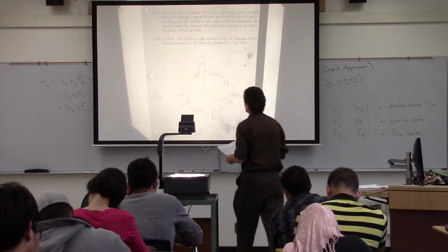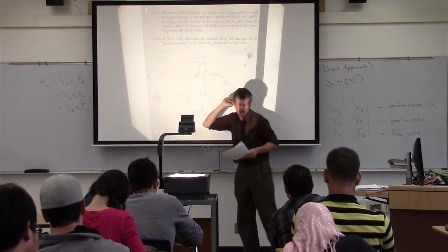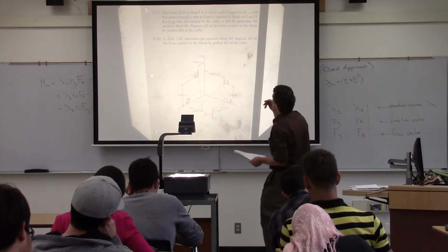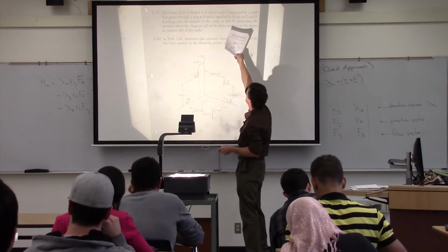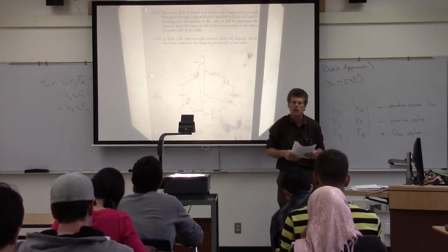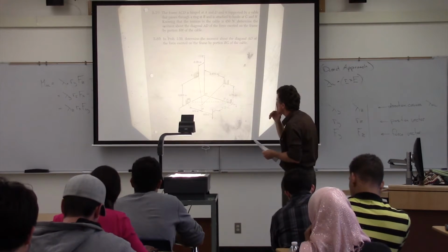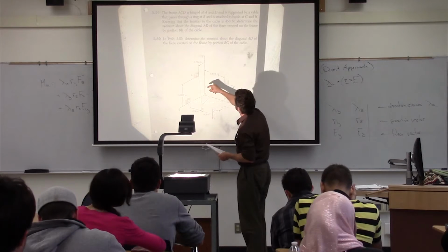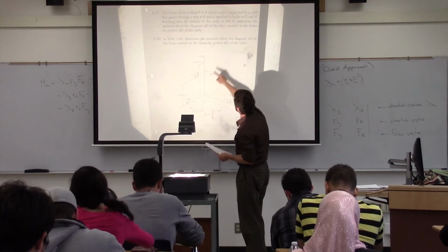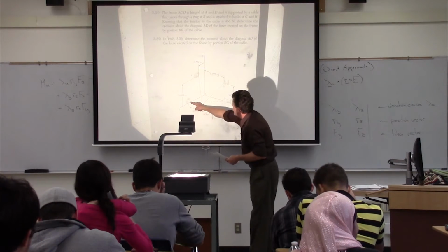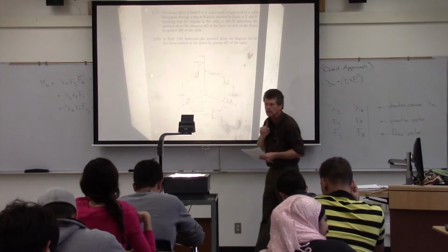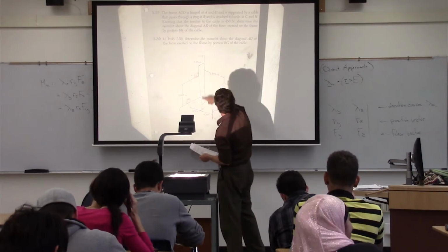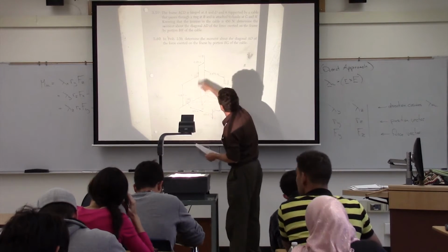OK, so we're going to do 60. But I put 59 up there basically because we need some information from it, specifically the tension in the cables, which is 450. OK? So what we've been asked to solve in 59 or in 60 is the moment about this diagonal AD. So it's along a line. And it wants us to solve it just for member BG.